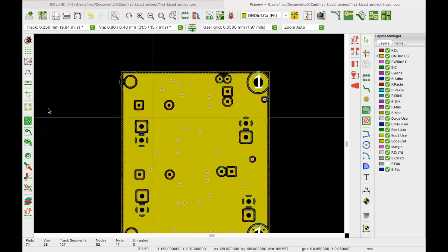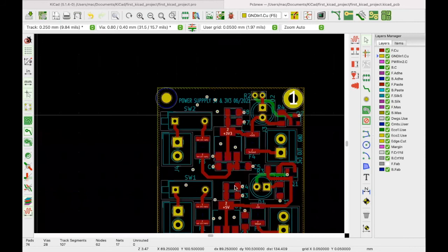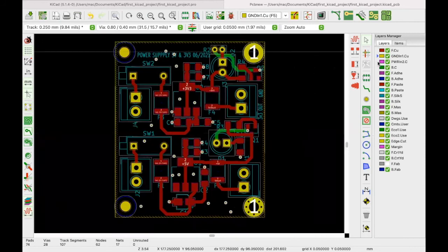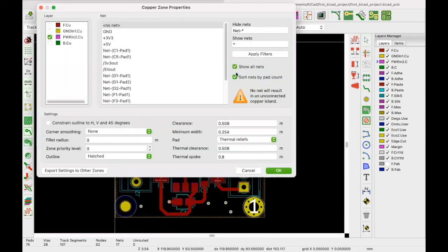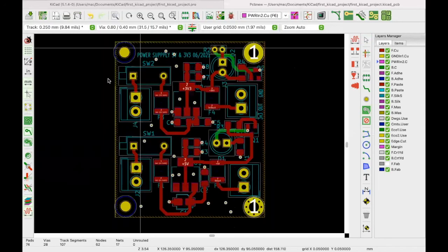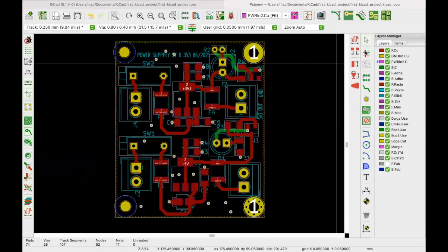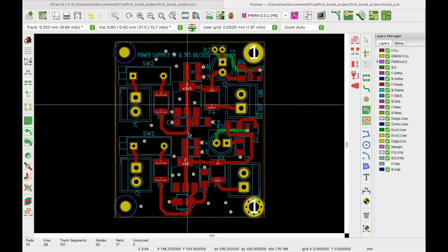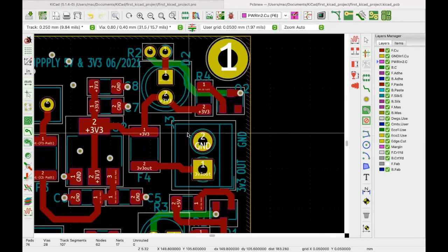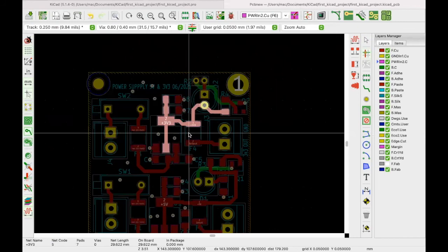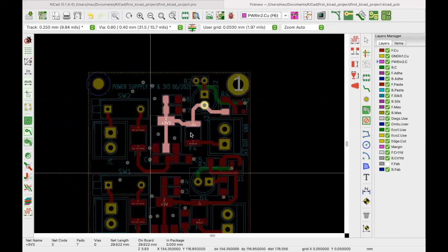So again, if you want now to do the top, the VCC, say the power, you can just hit this, select this. Again, left click. So it will again prompt you to select which power. Let me show you a very interesting tip here now. Say you don't want to select that. You remember this tool here that shows us highlight net, yeah? So you hit this, say, let's say we want to use our internal power as 3v3.